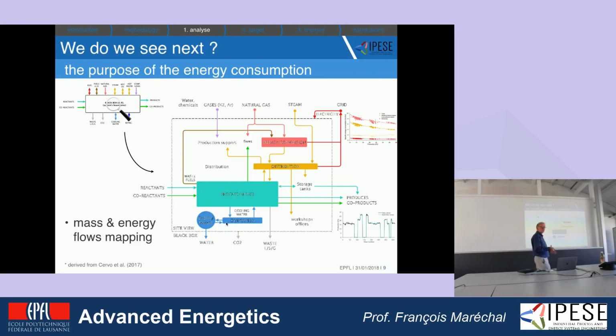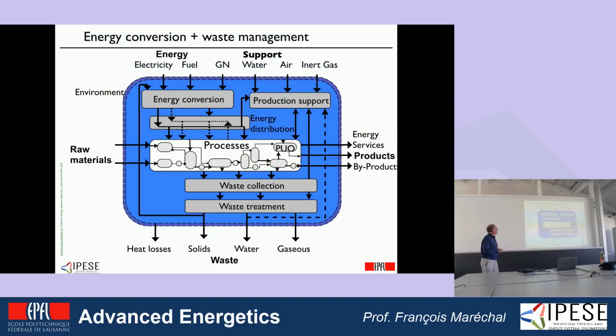So something that I'm looking at there is to try to understand in which pipes the energy that I have seen as an energy bill is flowing. Okay, is it in form of steam? Is it in form of hot water? Is it in form of compressed air? Is it in form of cooling water? Okay, the in and the out are therefore converted into flows in pipes. Okay, and if I'm doing this, then I will have a much better understanding of what is happening inside, which allows me then to have the complete picture.